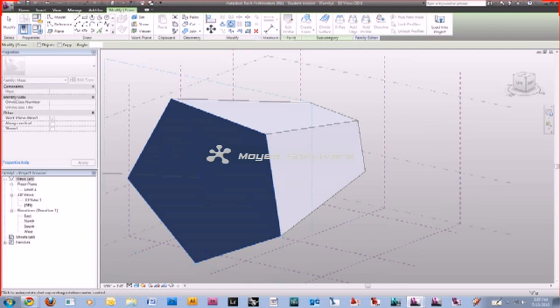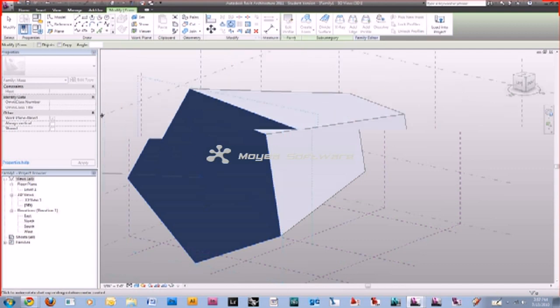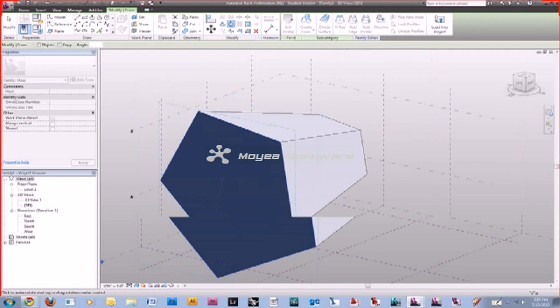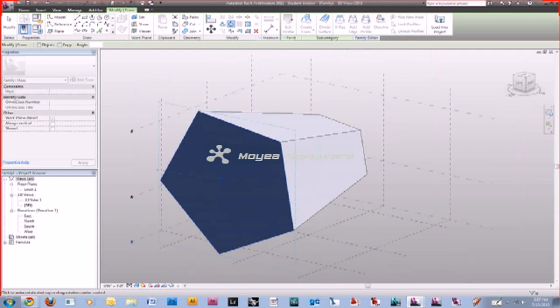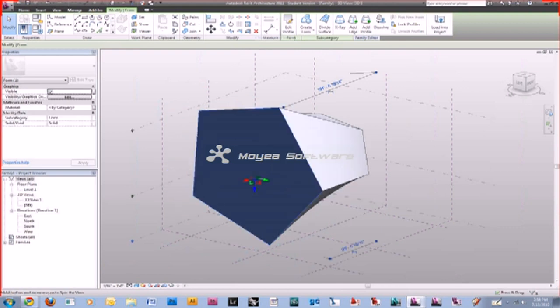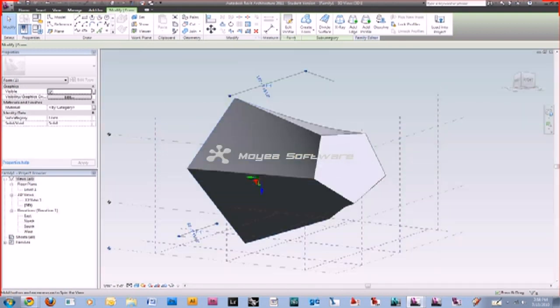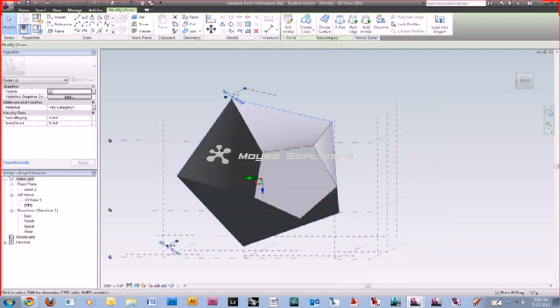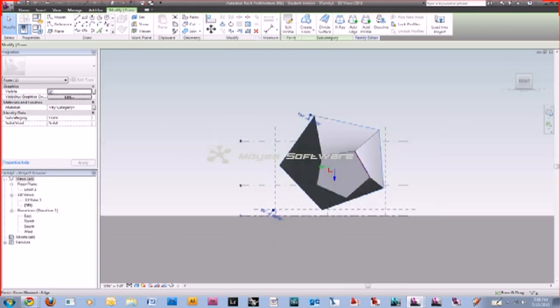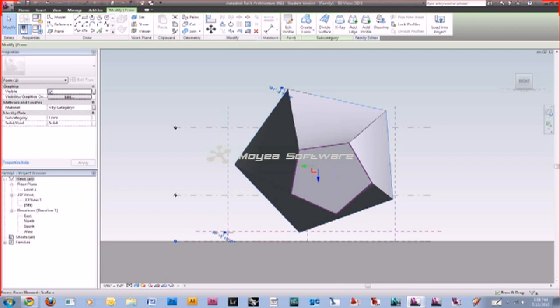It may be better to actually show them the rotate from a point instead of the center, because the center is obvious: it's going to twist it around the center. So drag it to one of those other points. Let's rotate around this point and see what happens. Probably give us an error. All right, so it rotated around that point, which you might not be able to tell at first, but if you went to an elevation view, it rotated the shape higher up in the air as well as twisting it. So now the shape has more elevation up above than it does below because it had to rotate up toward that point.